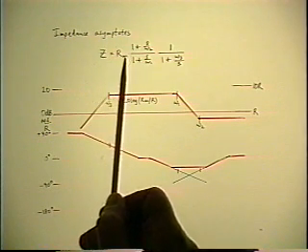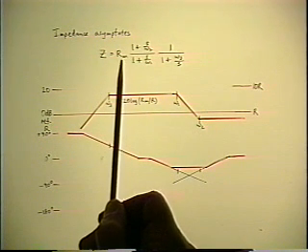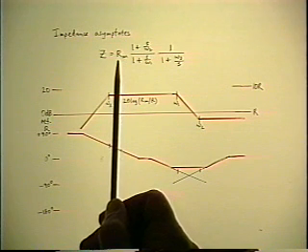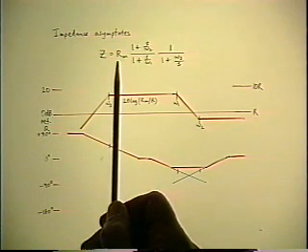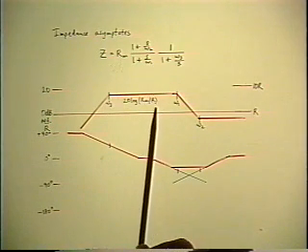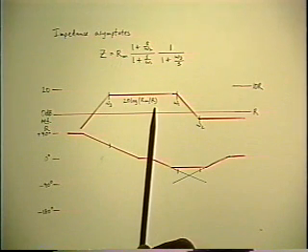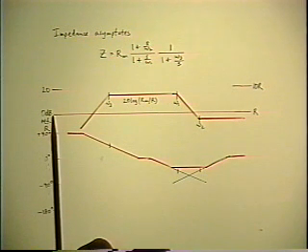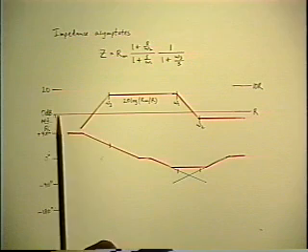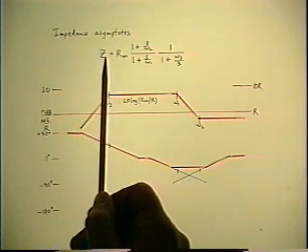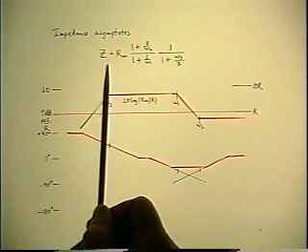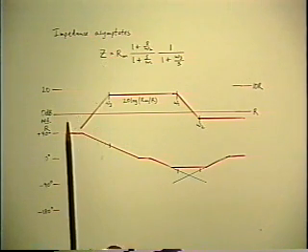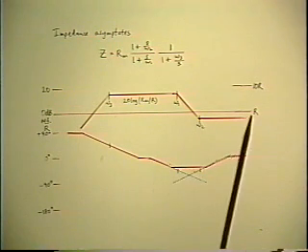And that makes this coefficient dimensionless again, just like a voltage gain. Then you can convert it to dB by taking the log and multiplying the log by 20. So the reference resistance that you have chosen then corresponds to the 0 dB level, because 0 dB means a ratio of 1. So when you have 0 dB for the magnitude of the impedance, what you're really saying is the magnitude of the impedance is equal to the reference resistance.